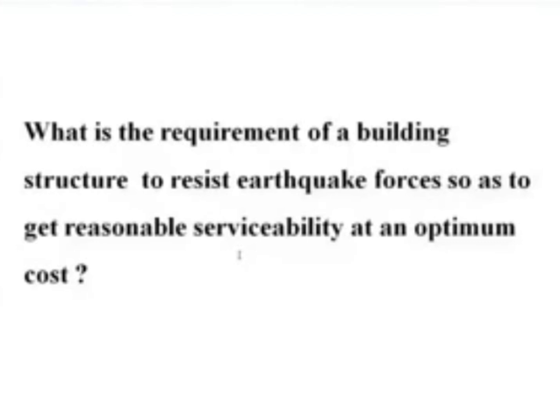and what you have to do, you have to accept a particular damage limit. That is, reasonable serviceability means everything should be within a particular limit so that it can be repaired. Suppose the main frame of the structure is all right, everything is fine, but the walls are cracked.